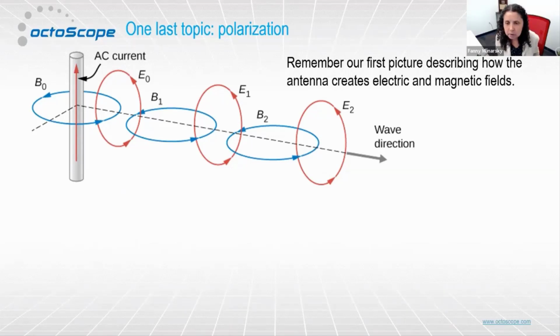Well, matching networks are very common. I mean, you always have one at the antenna. It's part of the circuit design, I guess. They are the ones that optimize return loss. Did I answer the question? I'm not sure I completely understand. But they're always there at the antenna. They match the antenna to a 50 ohm, usually 50 ohm connection. And the chip, whatever the chip is driving the antenna, it would be driving it through 50 ohms.